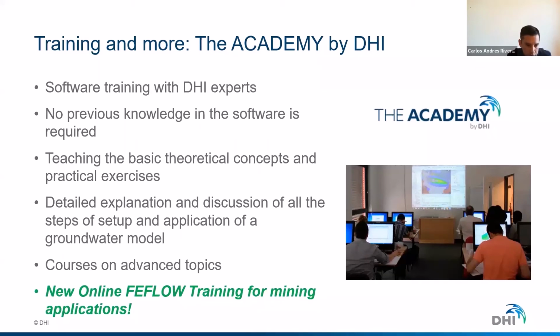And I would like to draw your attention to a new training course that we are rolling out now. It is a special training course for mining applications. So we plan to offer multiple modules, and we start with module 1, which is related to opencast mining. Here you will learn all the different topics of how to simulate open pits in the context of mining applications, use FEFLOW to build the geometry of your pit or pit shell, how to set seepage boundary conditions, estimate volumes over time, set up drainages, etc.